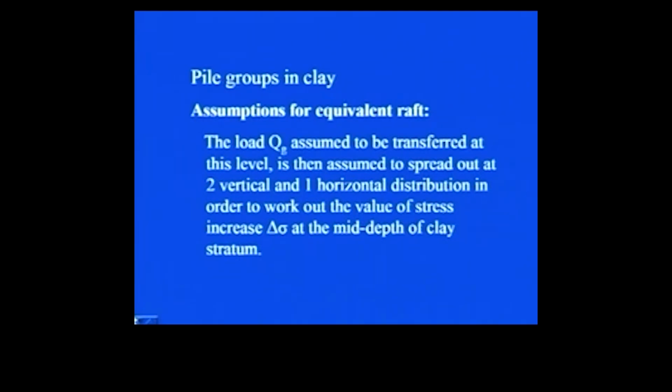As you have seen in the shallow foundation chapter, how you were calculating the settlement below any footing or foundation system. Usually what we see is that when the raft has been placed at that particular depth, then the load obviously will get transferred to the soil lying beneath that. So, it gets transferred in a 2 vertical and 1 horizontal system.